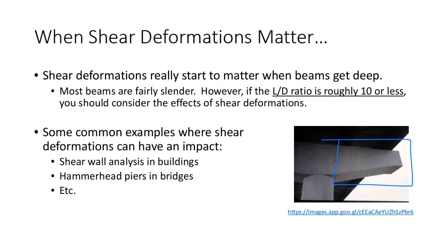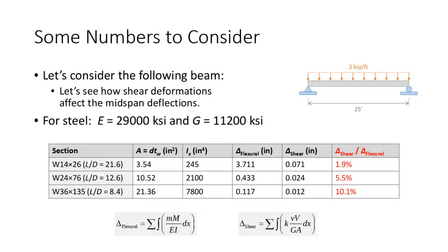And so normal little m, big M over EI would not be enough to compute the deflection of that beam. Now granted, this is also a tapered beam, so it makes the integrals a bit more difficult, but even if this was just a solid depth, it would be deep compared to its length. And so I want to show you some numbers.